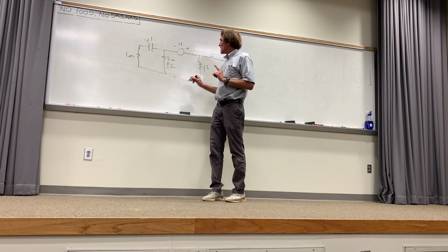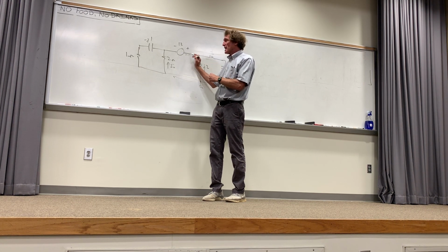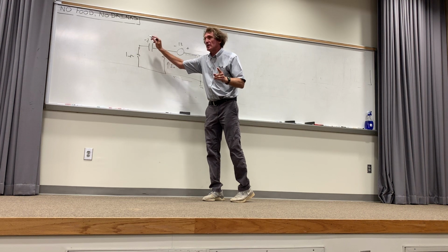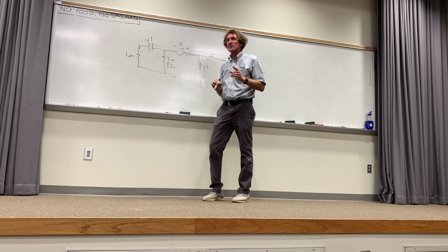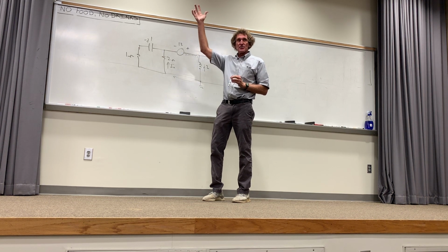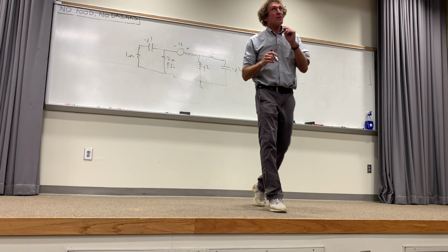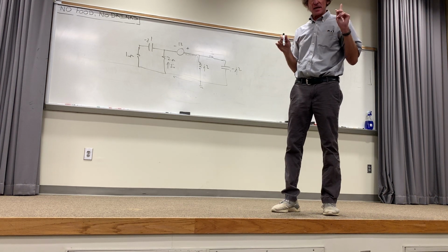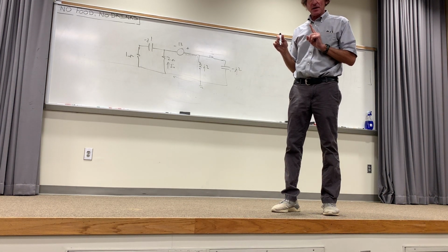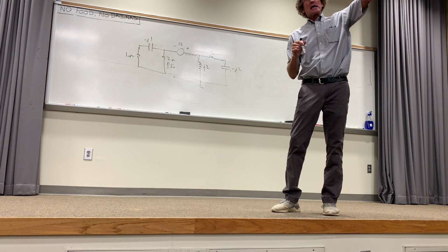Now, once we had the I flowing here, to get I naught, we'd simply take that I and multiply it by the opposite impedance over the sum of this plus this, and we could do it with current division. How many understand what I'm talking about there? That's using current division by getting the total current very easily by just combining things. That's one way to do this problem. And you would get the right answer. Did you do it that way, by the way? I did not.